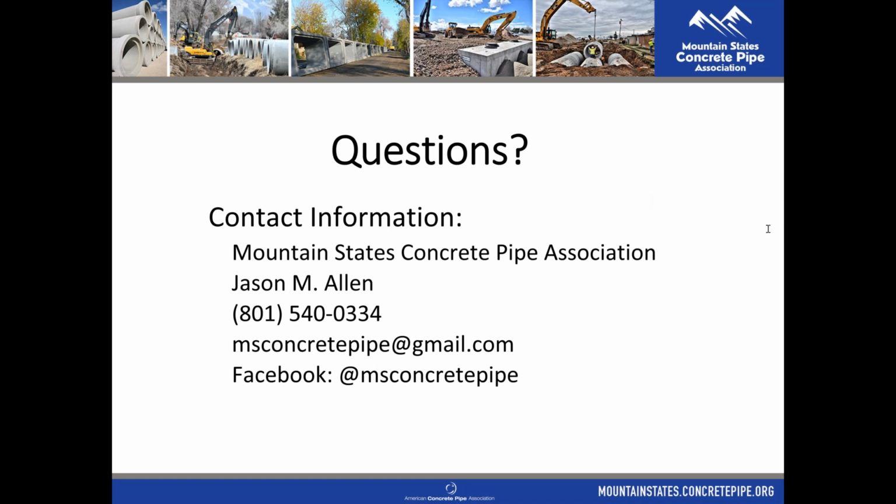I just lost my train of thought, but I was going to say something else on that. Oh yeah, for reinforced concrete pipe, we recommend you use the standard trench detail from ASTM C1479. So there's really no need to modify the lift thicknesses or any of that; it's all pretty much standard. As far as the design from the project engineer, because we are guaranteeing the structural components of these pipes, that they will withstand certain loads based on the class that you specify, it's significantly less work in the structural design and putting that trench detail together. So just keep that in mind.